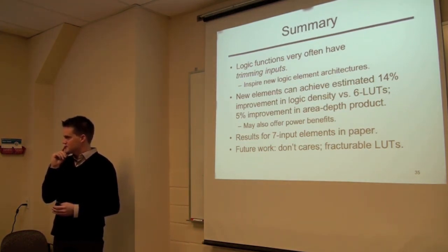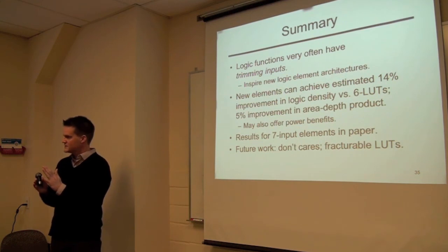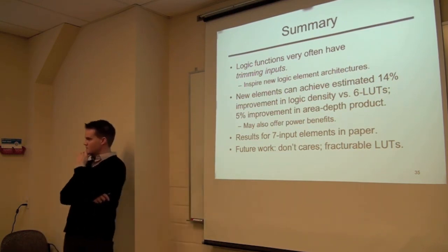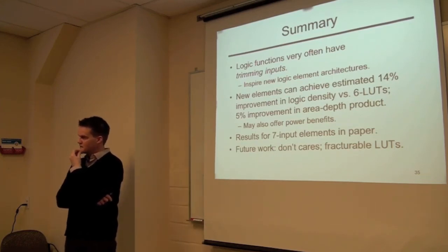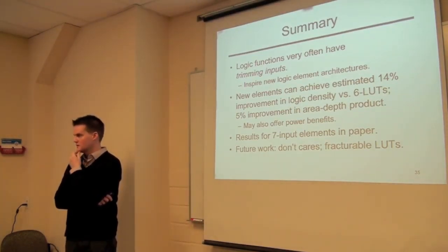So basically once you hit the logic block, it was a full crossbar to hit any LUT input inside there. So wouldn't we have to have routing up to the LUT input pins to properly investigate that? It's probably two separate questions. Nowadays most clusters are depopulated, so really you should model that. Sure, but let's say you just ignore that, because that's arguably a separate question.